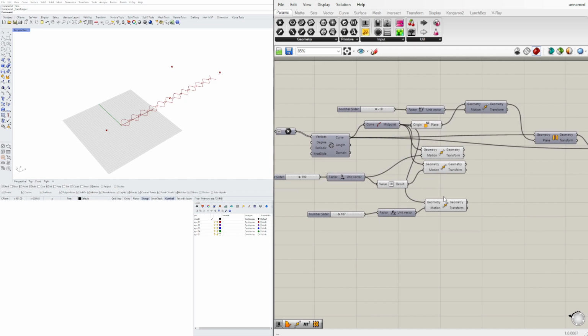With these 3 points, this one, and these 2 down here, we can create an arc. I'll double click here, go to Arc 3 Points, and plug in first value, point A. Second value is going to be this geometry, which is the point that we moved up, and this geometry that we have here.